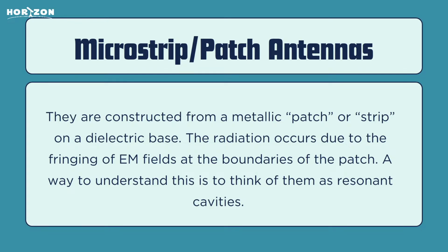If somebody knows how lasers work, they have a certain cavity from which we can get a resonant effect. And because these are also a different sort of medium inside of a dielectric medium, there are standing waves that form here also, which radiate out and give out the radiation. So in a way, they can be treated as transmission lines.